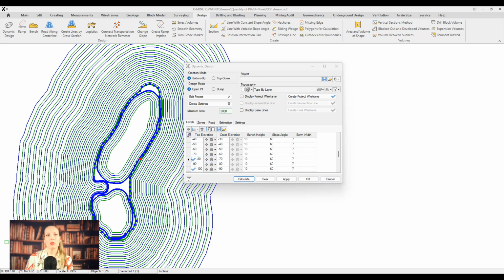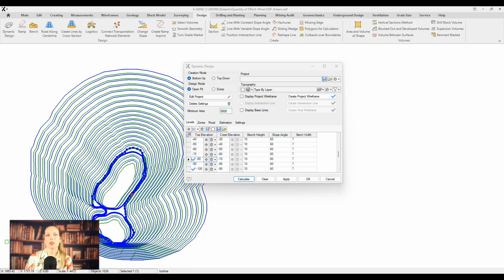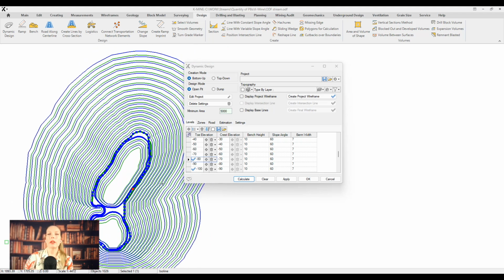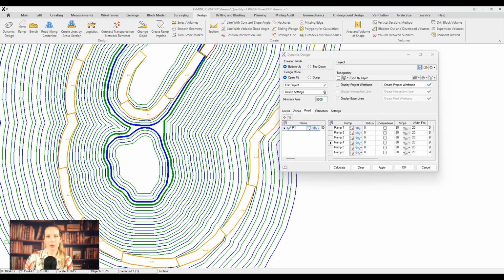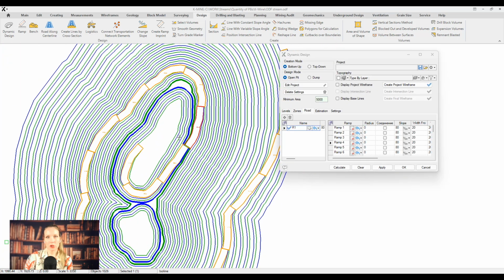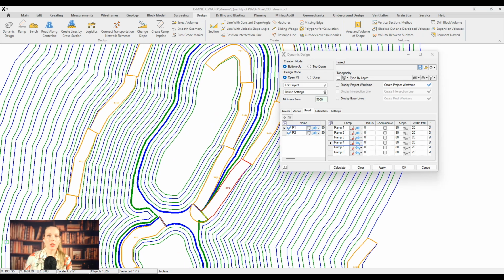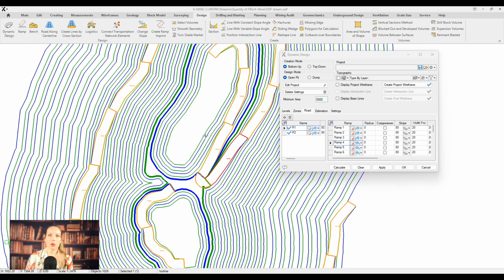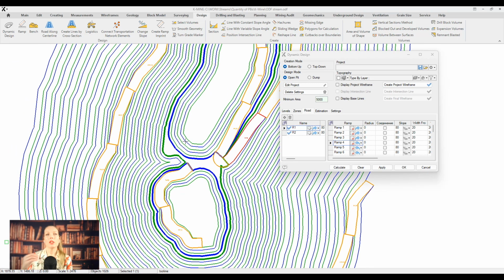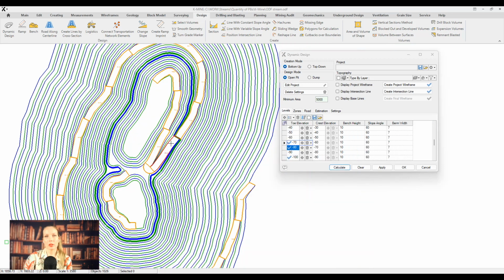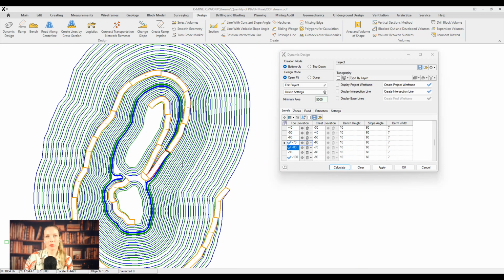We add one row, then another, turns, connections, and so on to make sure every part of the pit is accessible. Each section of the project must be mineable. This must be ensured at the design stage of the final pit contour, and all approaching roads must be interconnected to ensure flexibility in the transportation of materials.